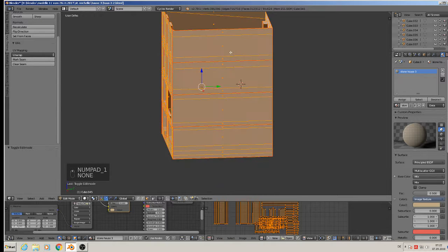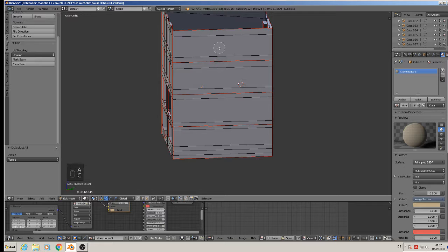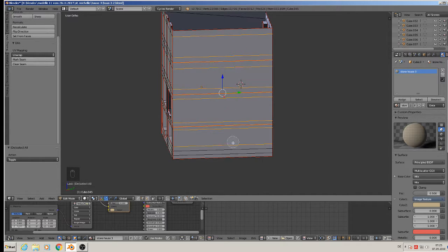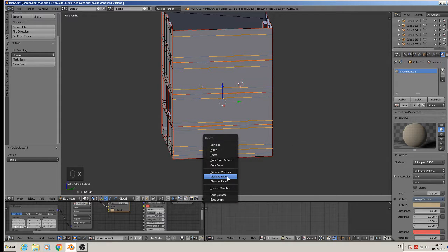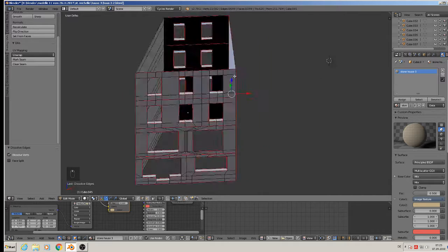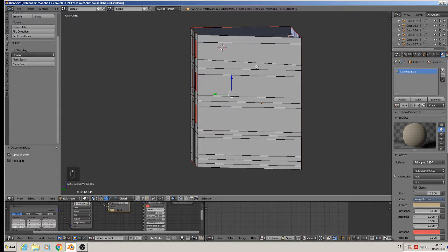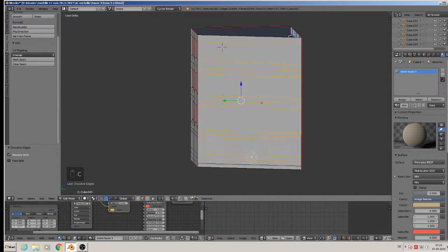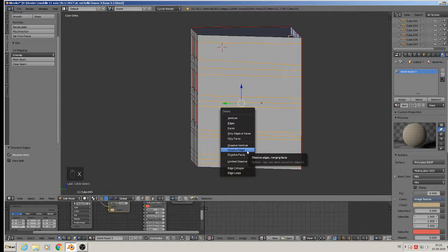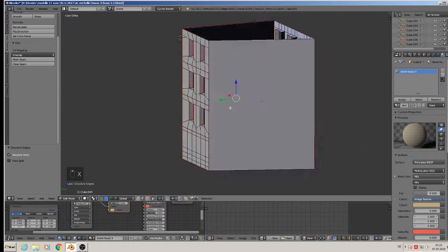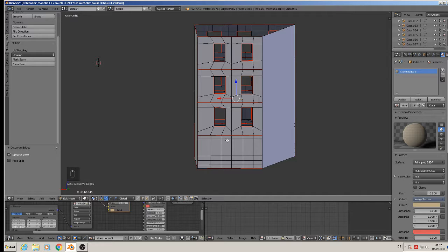Then we go on. We delete what we don't need. That means circle selection simply, and here the edge selection. Go down here, and X, dissolve edges. One side cleared. The other side, same circle selection. Go down, X, dissolve edges. Done. Here the same. This part.